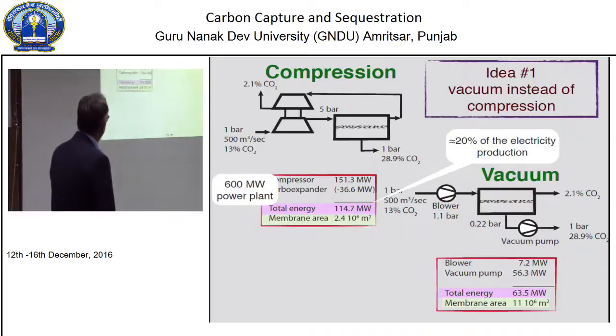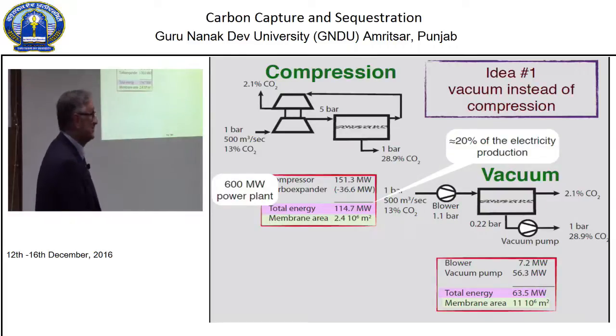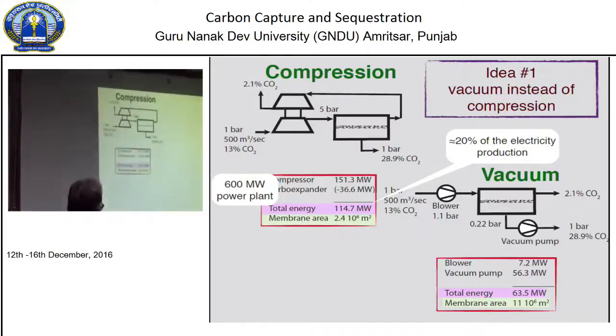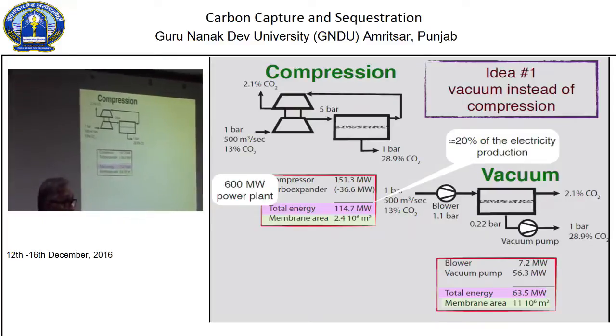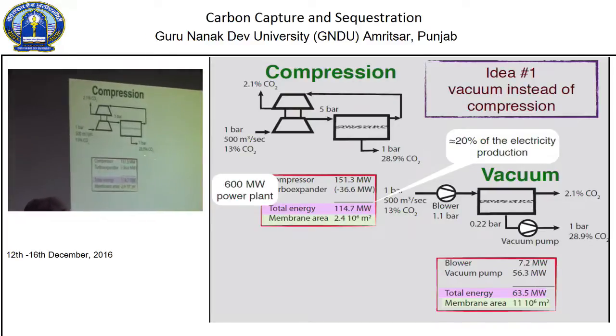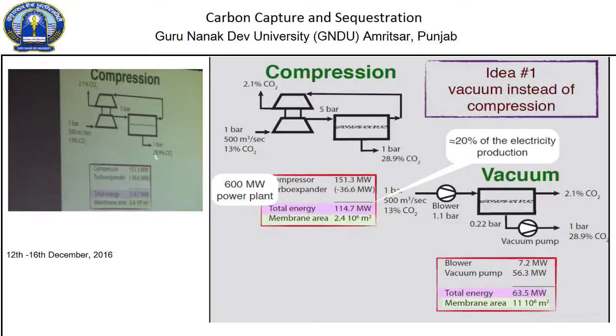So, for example, here's a process flow diagram, for those of you who are engineers. This represents the membrane. Here's the membrane here. The gas comes in up here, and it's been pressurized by this turbine to 5 atmospheres. And so CO2 comes through the other side, and if you solve the equation for a typical membrane, you get almost 30% CO2 at 1 atmosphere.